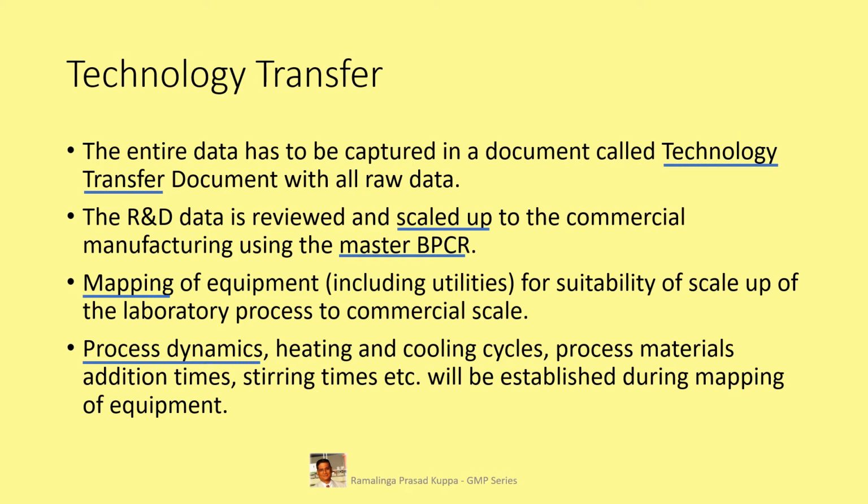Process dynamics include the actual timings that are required for commercial scale, and should be captured at this point. Addition times, mixing times, heating and cooling times, rate of heating and cooling, drying times, etc. will be different from a lab scale to a commercial scale.